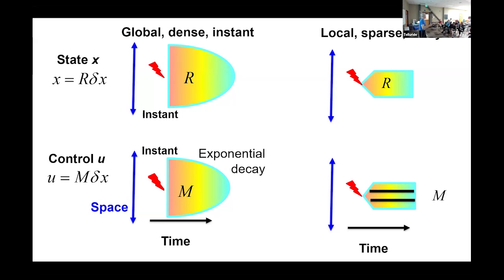And all of that can now be done in a convex optimization problem. All of you are going to guess right away. We're going to do a lasso regression. We're going to do all the usual stuff you do in convex optimization to decide where do we put the sensors? Where do we put the actuators? But the nice thing is it's all convex, it's all closed loop. And we can systematically trade off the cost of communication, the cost of actuation, the cost of sensing. How dense do you make the communication? How fast do you make it? All that becomes possible in trade-off space.